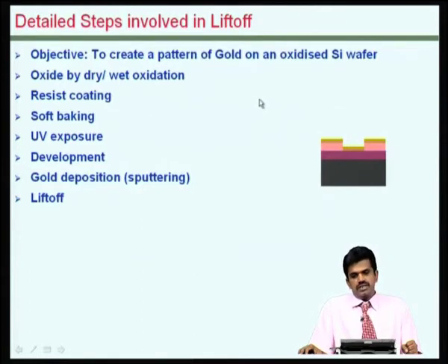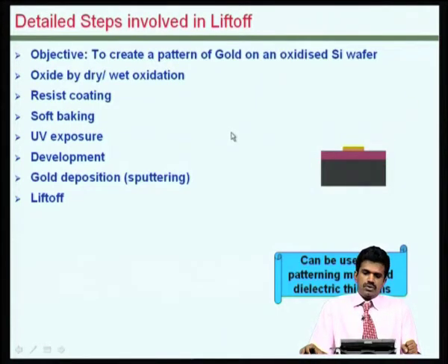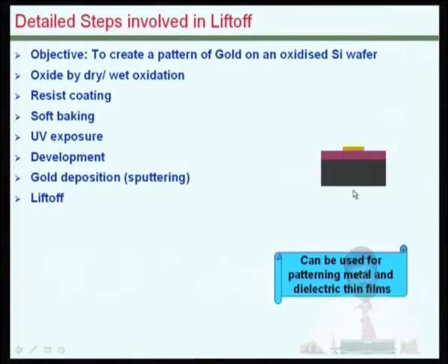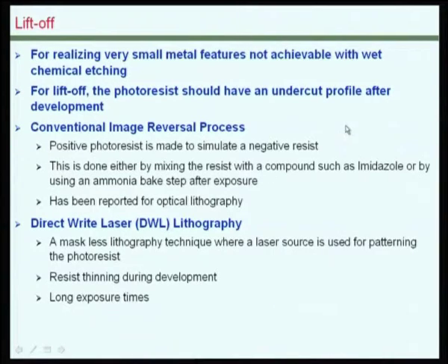There are some innovative schemes which could be used, so that we can ensure that there is a discontinuity between these films, so that the final removal by dissolving the resist material would result in removal of the unwanted metal and not the metal that you would need to keep over there. So, the Liftoff technique in fact can be used for various materials, including metals and dielectrics.